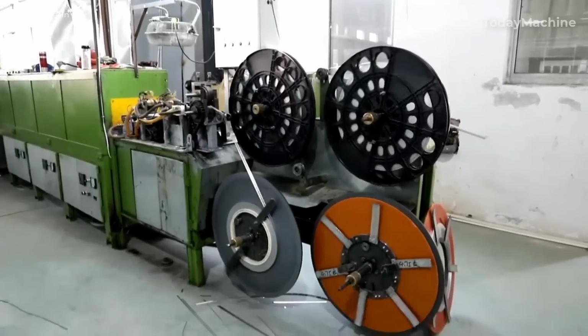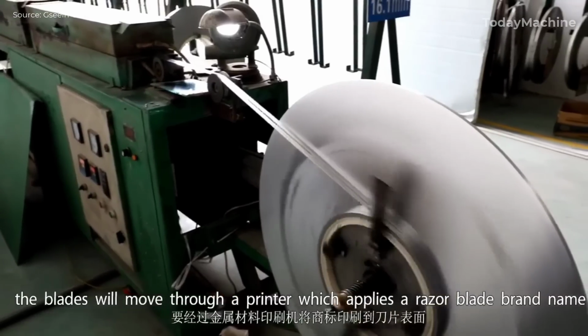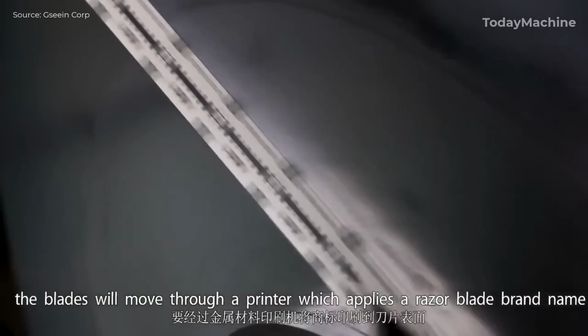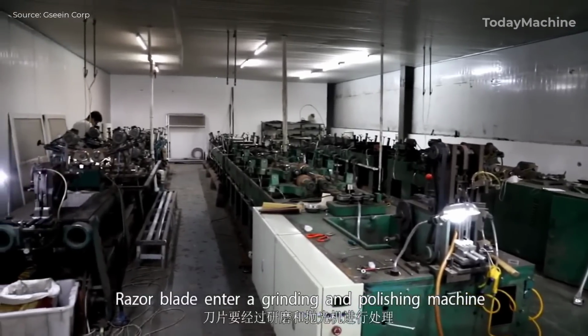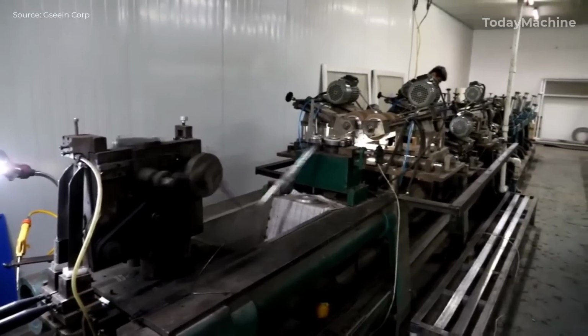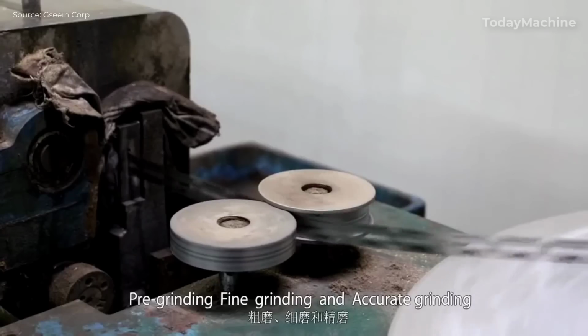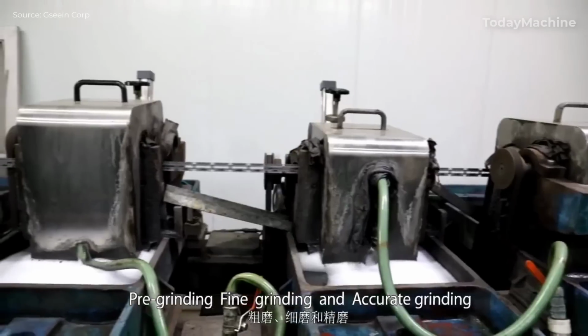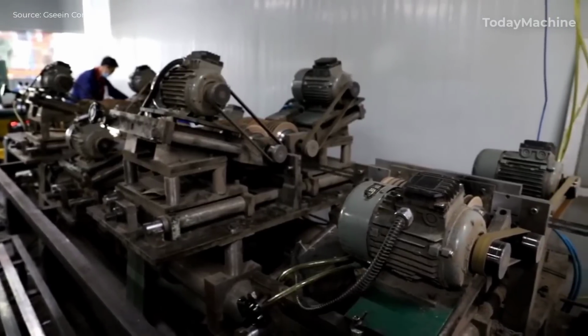For double-edge blades, the next step is branding. The blades move through a printing machine that applies the razor blade brand name onto each blade. In the second stage, the blades enter a grinding and polishing machine, which has 3 grinding stations: pre-grinding, fine grinding, and accurate grinding. This multi-step grinding process is essential for creating a super sharp cutting edge on the blade.